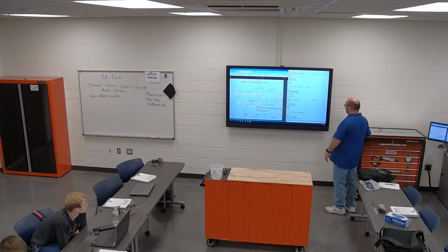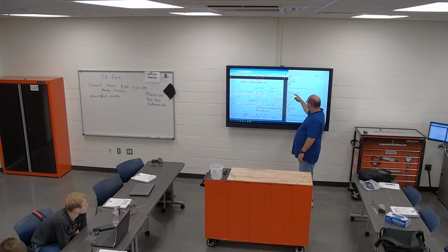Are you guys starting to see a pattern here? Yep. This is pretty much all the same. G54 is your offset. Here's your height offset, G83, and then Q2. You guys remember what that is? Peck depth.